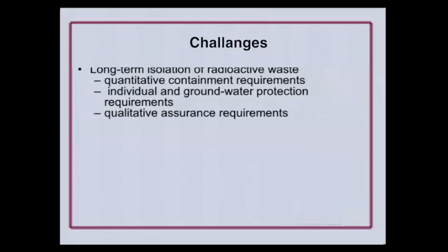One, long-term isolation of the waste, both quantitative containment requirements and qualitative assurance requirements that it's going to be disposed of in a manner in which the public safety will be maintained and the impact on the environment minimized. It also includes individual and groundwater protection requirements. That's kind of the principle or philosophy for the standard as far as dealing with transuranic waste.